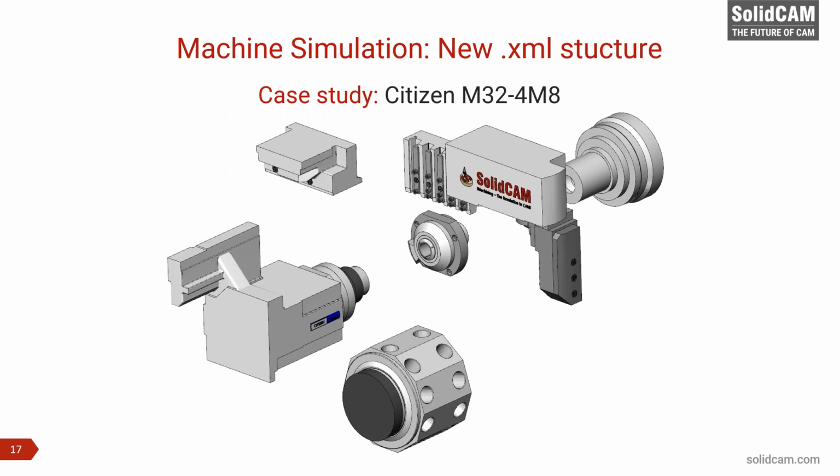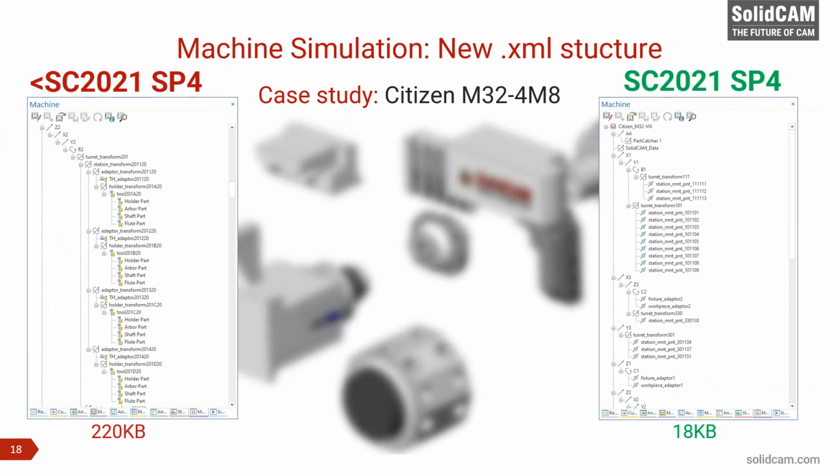To generate the XML structure in the new version, you just need to open the new SolidCAM, and the procedure is the same. Right click on the VMID, export to XML, everything is there. You have nothing more to do. So let's jump into this.